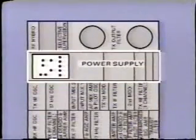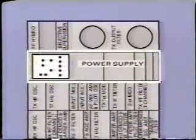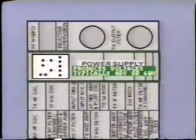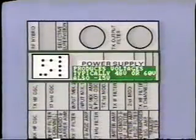The second tier of equipment is devoted to power supplies for the carrier. It contains modules to filter or condition the incoming power, as well as modules to produce the special voltages needed by the electronics, typically 48 or 60 volts, and also a minus 15 volts.